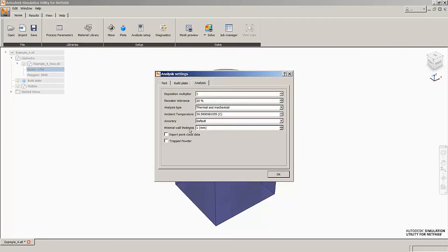So first you want to enter a minimum wall thickness, which is just roughly the thinnest section in your CAD file. So it doesn't have to be an exact entry, just a rough approximation, and this is going to let us take an initial guess at what a reasonable voxel mesh will be, and then we can view that mesh and iterate using the mesh preview function. So I'll leave this minimum wall thickness at 1 millimeter. That's roughly the minimum wall thickness in the geometry that I've imported.